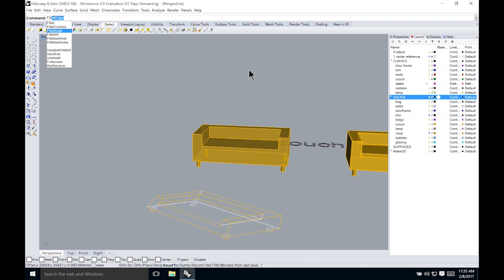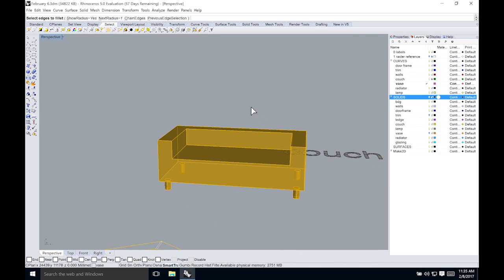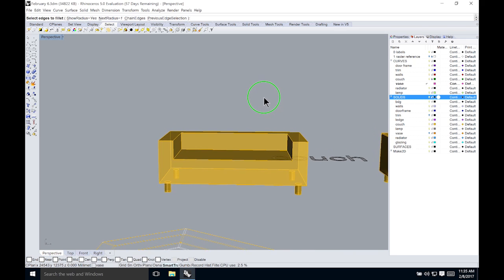so there's again an order to things. So if you already select your edges, then the number you adjust is going to be current in the next operation. So before even selecting anything, I'm going to change this to 50 and then select my edges.